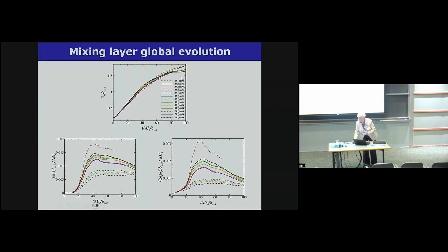So basically, they're starting with just about the same composition except for these trace species. So if you look at the momentum thickness, the growth of the layer, it's about the same. So dynamically, from the point of view of the dynamics, you can't see much of a difference. But let's look here at the positive span-wise vorticity that starts by being 0.